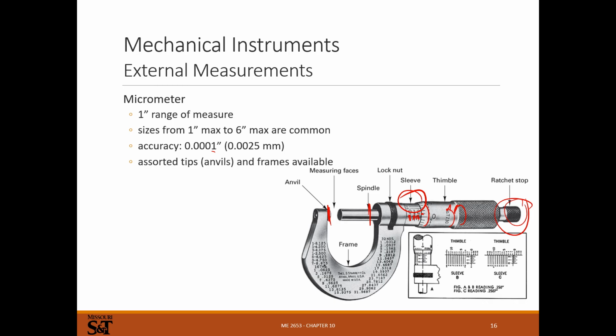Once you've done it a few times, it's second nature. It's really easy to measure with these things. And it's a pretty simple device for measuring down to a tenth of a thousandth of an inch. There are different little anvils you can screw in here for measuring different things. You need to spend money on these. Your measuring equipment's the most important thing out there.